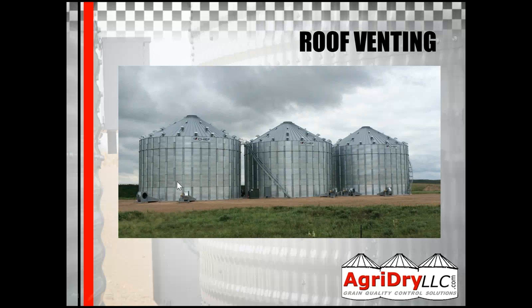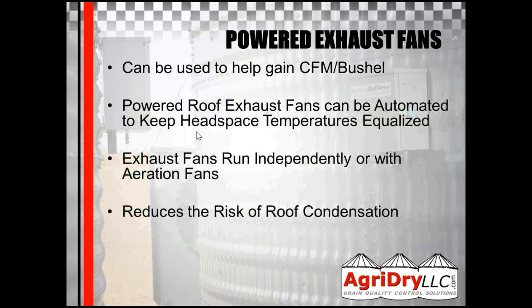So remember, the first picture just had the roof vents down by the eaves. Now in that simulation, what we want to use to get that airflow across the entire bin from the center to the outside, there's literally 3 layers of roof vents: one towards the eave, one intermediate, and then the peak as well. So that air is simulating the best way to still have a roof on the bin, yet have that air tunnel to all those roof vents from the peak to the eave at that point. That's ideal for setting the bins up.